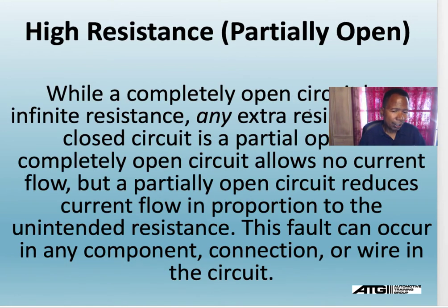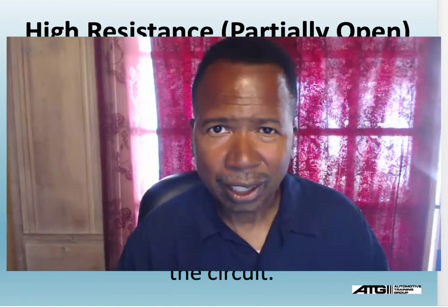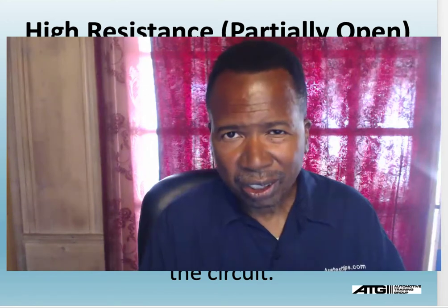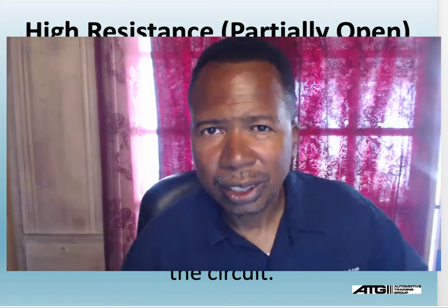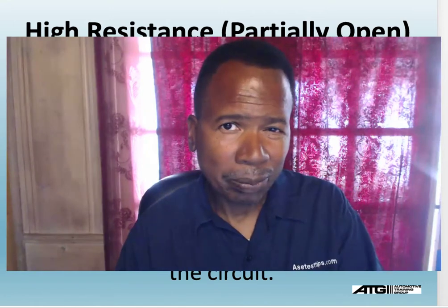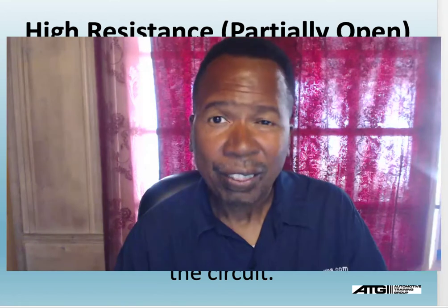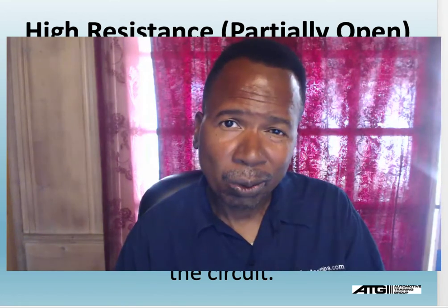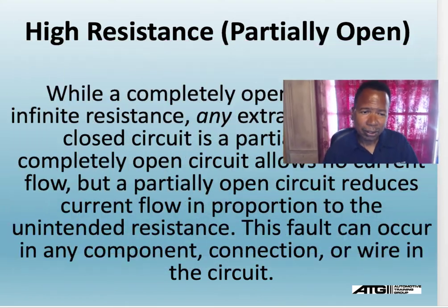Now, here's another thing people get confused. Let's go back to your car battery. The battery, the post, and the cable are all connected, but it has green and white crud on top of it, and your car doesn't start. That corrosion between the post and cable is causing an open, a non-contact. That's an open circuit also. Corrosion or resistance can cause an open circuit.